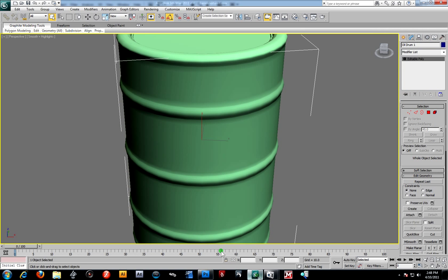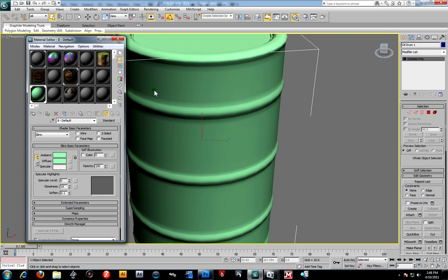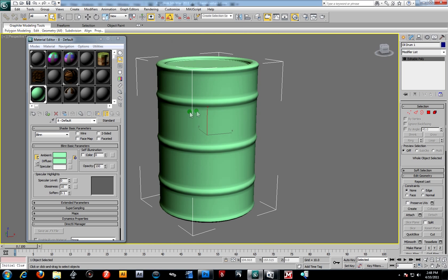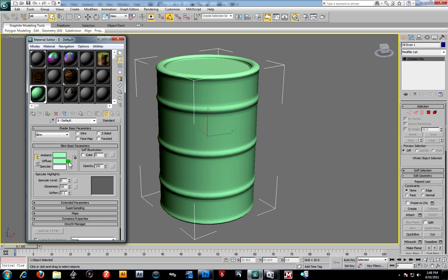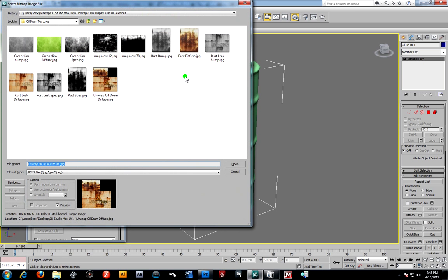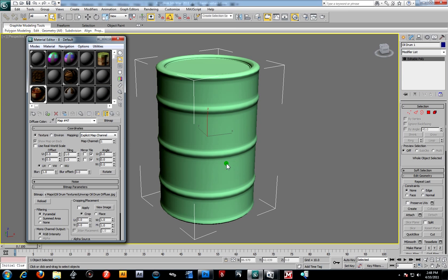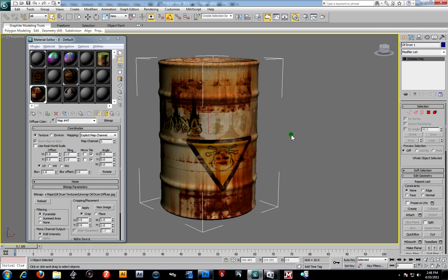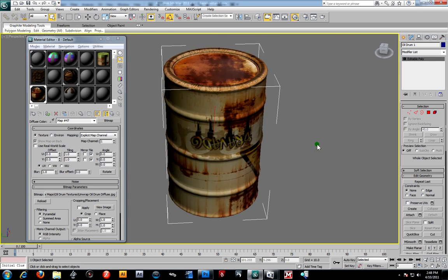So when I went back into Max here, I went into that barrel that we dragged those coordinates onto, or that shader, so we know that represents that barrel. I went to diffuse slot, bitmap, and then here's our oil drum. And then I just show maps in viewports. But as you can see, I didn't realize that it was upside down at the time.